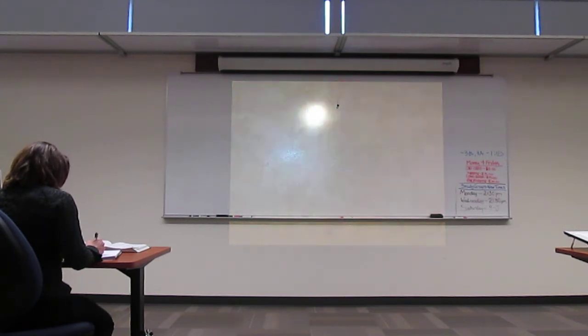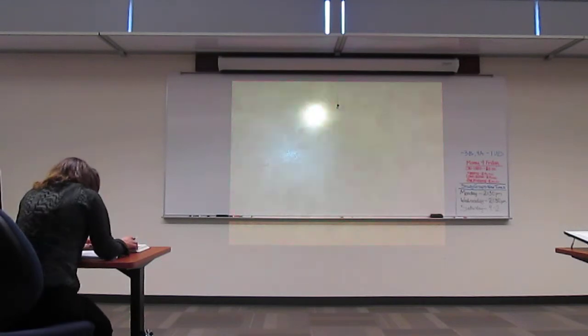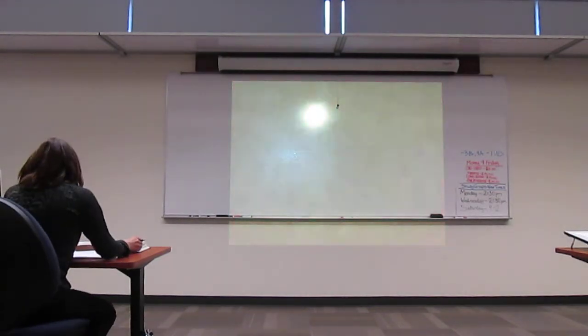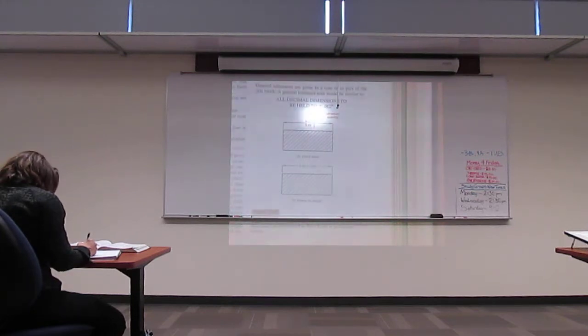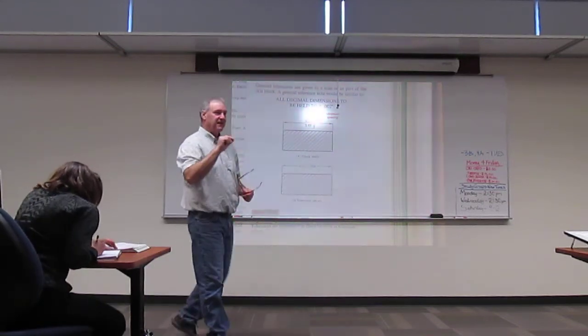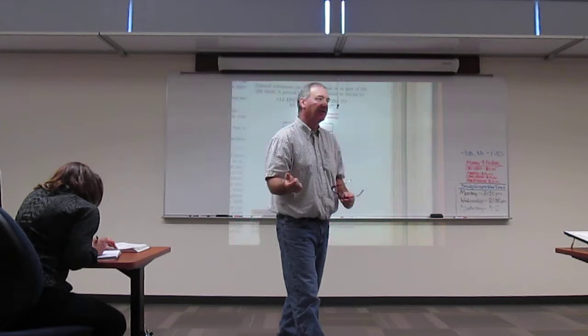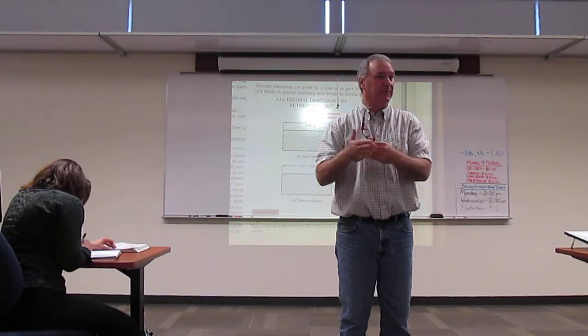First off, you can do direct tolerancing. Now, when I say direct tolerancing, as opposed to general tolerancing, I'm not really going to go into the general. You know what the general is. You're doing it right now. In the general notes, we put a tolerance, and that applies to every dimension on the object. Therefore, we don't put a tolerance with your dimensions.